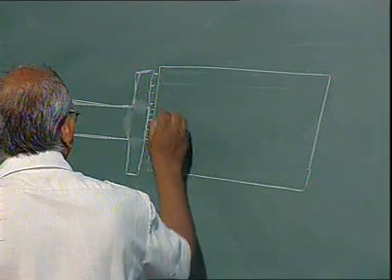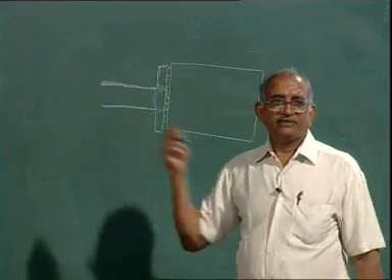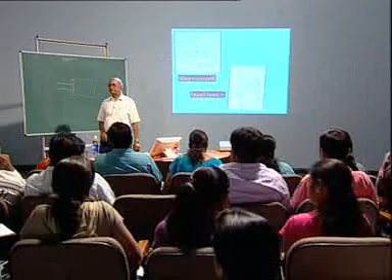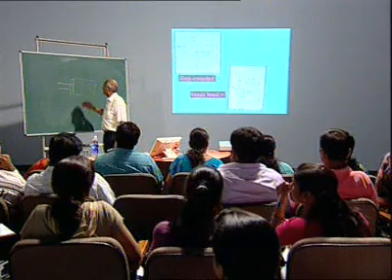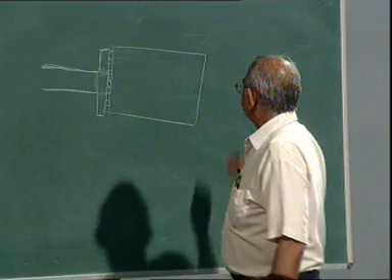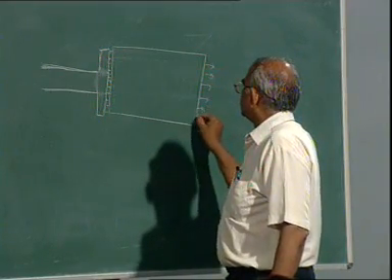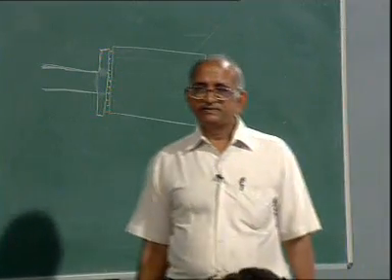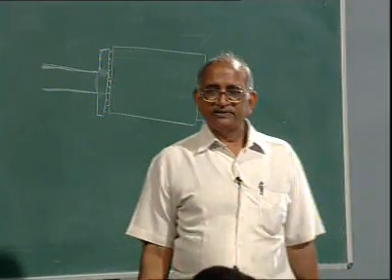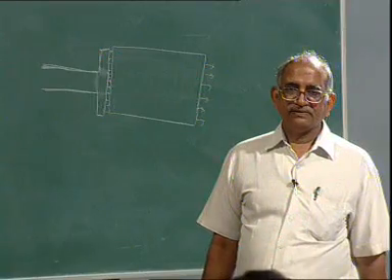So, this will give extra gap capacitance, and it will reduce the insertion loss of the antenna. Okay. Fringing part, in fact, in this case the fringing will get reduced. So, it is mainly this edge which will be contributing to the radiation, because you have introduced this gap over here, fringing will get reduced over here. Okay. So how can we decide the gap between the feed line and the patch?